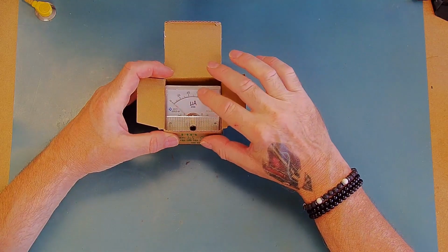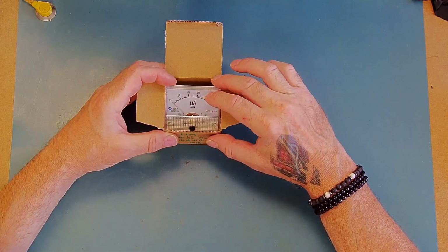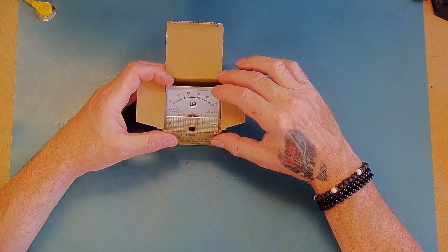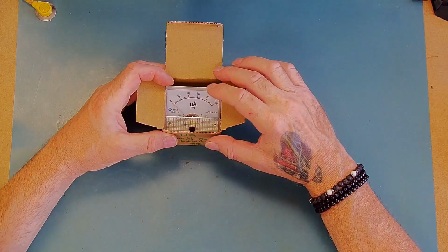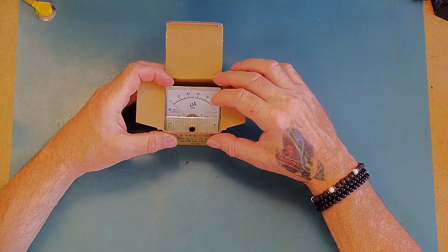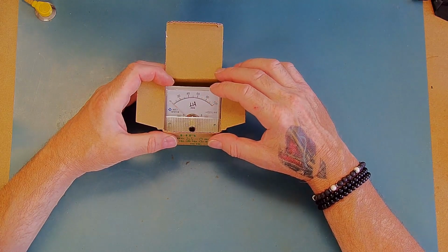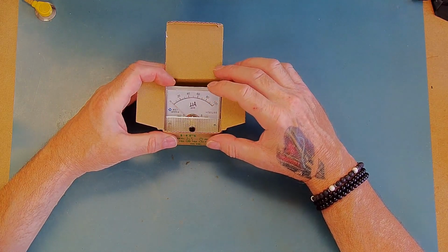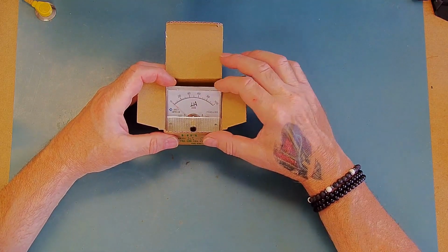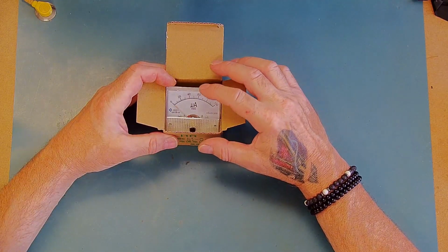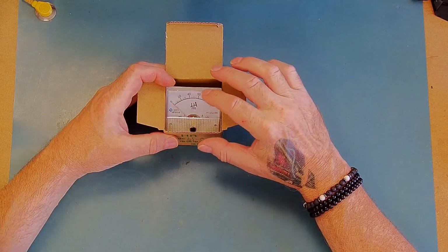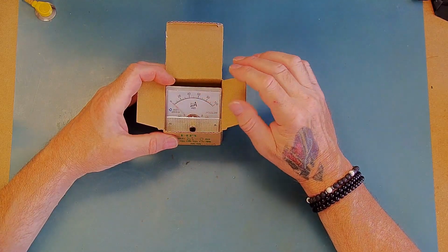Obviously, historically, these were really the only type of current meters that you could get before the advent of digital electronics. So many years ago, what you would have to do is to put what's called a shunt across the meter. Now basically all that is a resistor. So in this case we would just simply add a resistor across the back of the meter, and if we calculate that resistor correctly, then we can calibrate the range in factors of whatever we want.